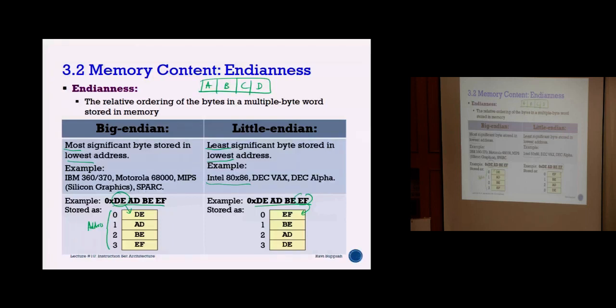For example, if I have an Arduino board and I want to transfer data to an RPi, you realize that your RPi Endianness and your Arduino Endianness is different. So when you try to send data over and you do not reconcile this rearrangement of bytes after you receive the data, then everything is going to be messed up. It's very important you understand the format in which data is stored in memory.